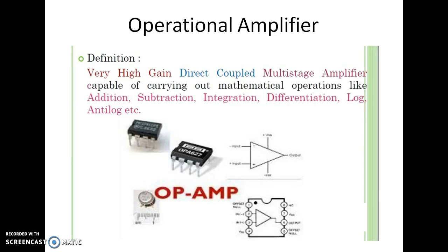As the operational amplifier is basically a differential amplifier, now let us discuss the differential amplifier and then analysis of the op-amps. Now here we will see first the introduction of the op-amps. I think in the first year of engineering you have learnt about the voltage amplifier using a transistor. It uses many other components such as coupling and bias capacitors, biasing resistors, etc. In order to get higher voltage gain, we will have to use more than one such amplifiers together. All this will make circuitry very bulky.